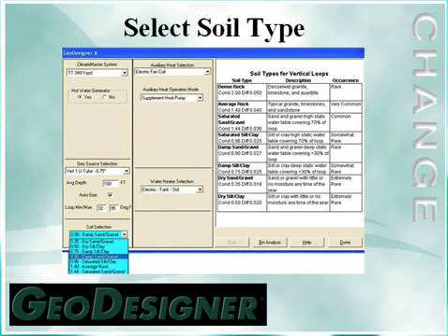Then we have to input the soil at our job location. Now, I know many times we won't know the exact soil at the site. I will typically recommend a damp silt and clay or a damp sand and gravel, and then when we go to do the actual installation, we need to verify at the job site what the soil is. Normally we'll know for a region if it's sand and gravel or silt and clay. It's confirming how much moisture is in the ground.